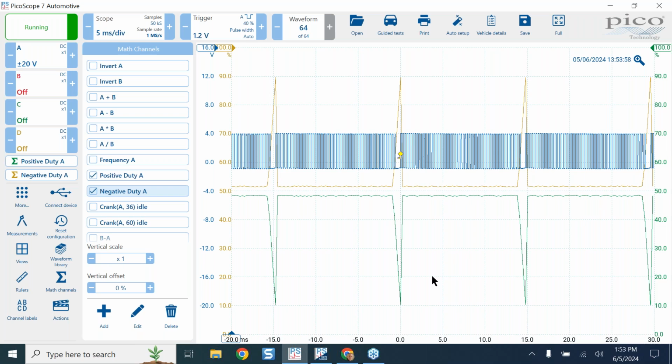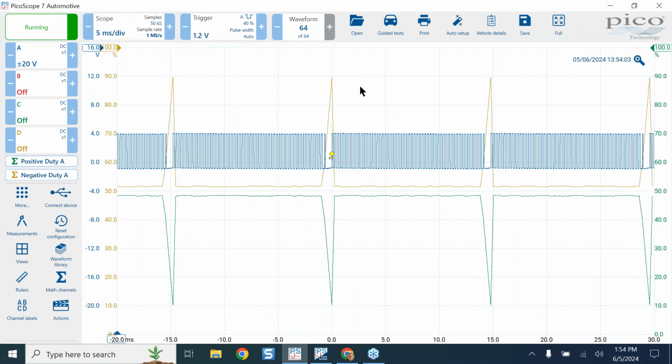And you may think, okay, what's the purpose of this? Why would I ever use this? Well, looking at a pattern, even if we triggered it properly, and you've got a very intermittent dropout on this crank signal. Maybe it drops, maybe it goes low, maybe it's biased low, maybe it's biased high, and it stays high. And it's not within the normal operating parameters that we have, which is this missing tooth, so many transitions back to another missing tooth. If it's outside that, are you going to be able to catch it?